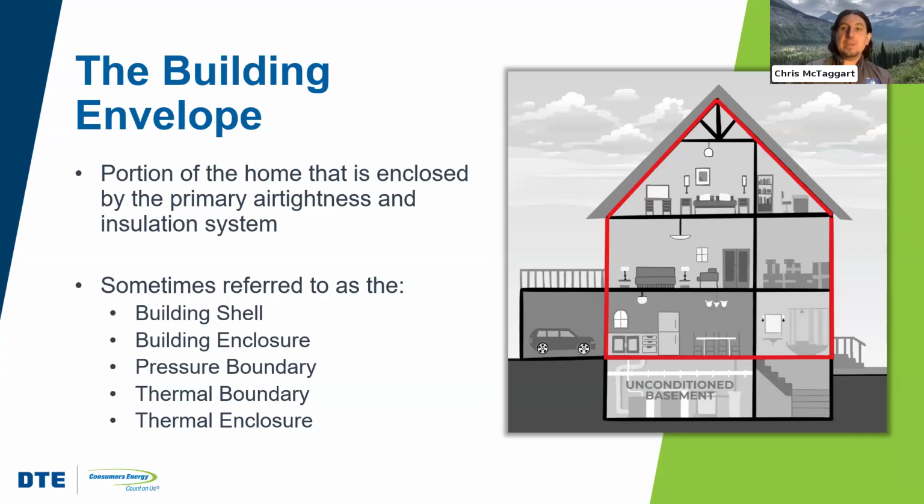They're basically at the floor, the frame floor over that unconditioned basement. Then we have our walls that go up the first floor, second floor, and then even the gable end walls, it looks like, for our third, an unvented roof assembly, so as to basically make the attic part of conditioned space.